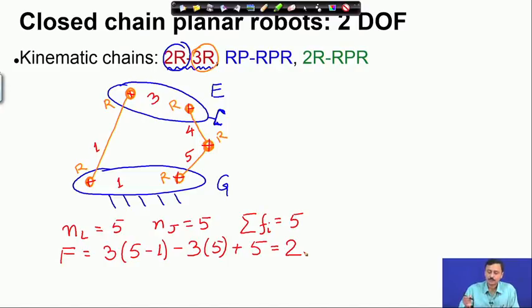That is why this is a robot. This is no longer a constrained mechanism. It will require 2 joints to be actuated, possibly this joint and this joint. So, the 2 ground revolute pairs can be actuated. 2 joints will be required to be actuated.